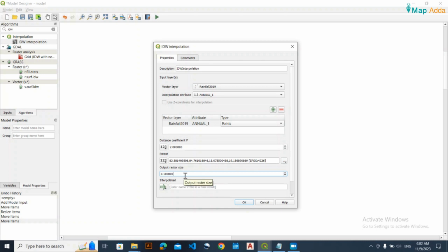It's really an important thing to consider, because if you don't give a sufficient raster size, you are going to get the output, but that output won't later be clipped by the mask layer. So be very careful to give the desired number of rows and columns, or this raster size, because a good estimation is very handy here.